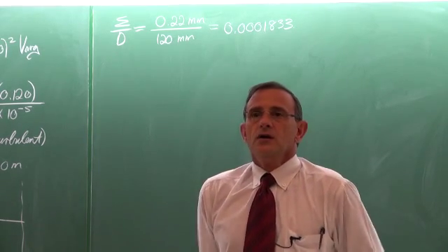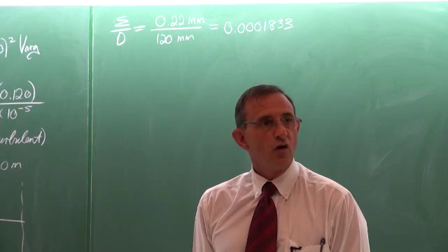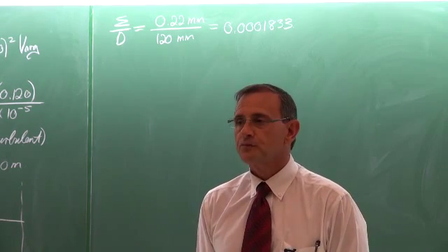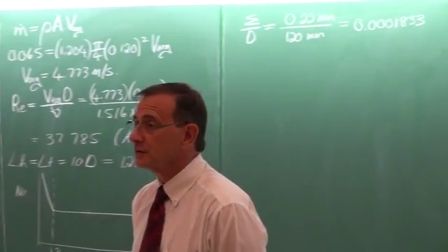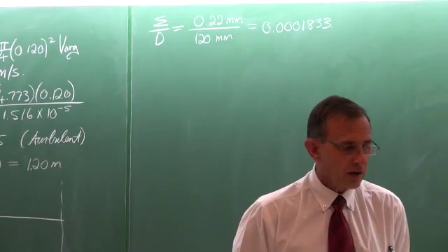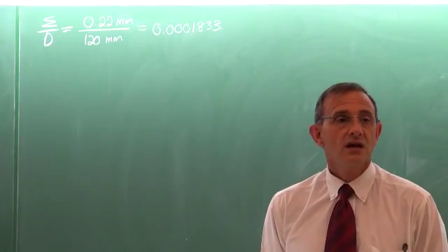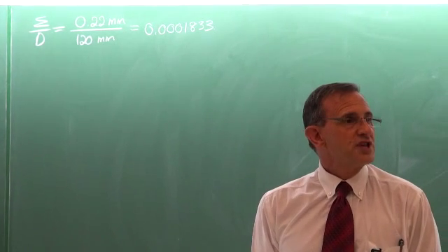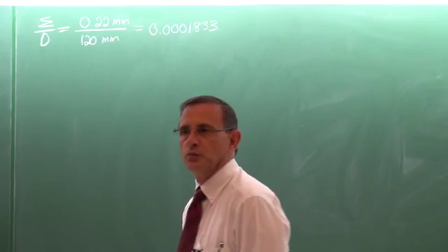Okay. So many of the equations you'll see in the literature are for smooth tubes, and not many are for rough tubes. Now, fortunately, and this is something that I've found through lots of experience, all the tubes that we buy these days are actually smooth tubes for all practical purposes.